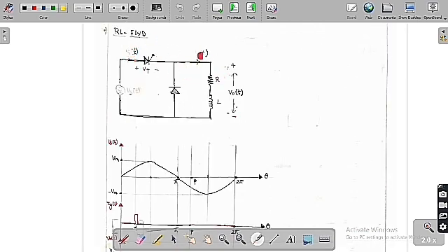So now we are going to keep a freewheeling diode, this is the RL load with freewheeling diode. Just now we studied the RL load, but now we are going to add this extra freewheeling diode, and everything else is the same. So the source voltage is plus or minus Vs of t, source current Is of t, thyristor voltage is plus or minus Vt of t, this is the load voltage V naught of t, the load current is I naught of t, and this is the freewheeling diode. Now we are going to analyze each and every aspect of this circuit.